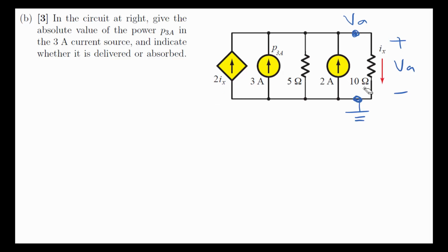So now to write the equation, we assume that the node we're operating on has the highest voltage and that all the currents flow out from it. So that node is actually all of these branches, and we're going to specify the node voltage equation in terms of the currents flowing in each of those branches.